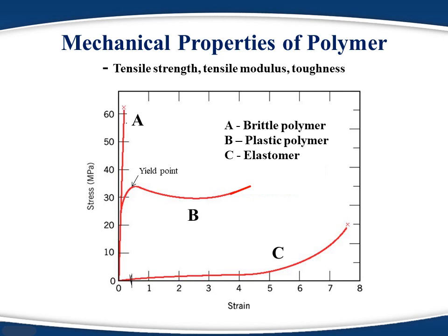Plastics are regular polymers which we use in our daily life. They show very unique deformation behavior. During the initial stage, very high stress is required to deform them, but after reaching the yield point, they show less resistance to deformation. And after reaching a certain level of deformation, they show more resistance to deformation, and finally break at a higher stress value than the yield point.